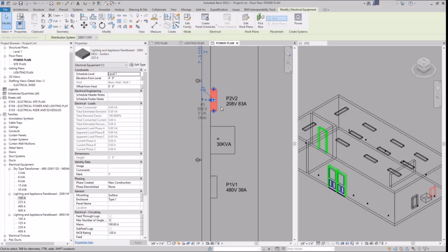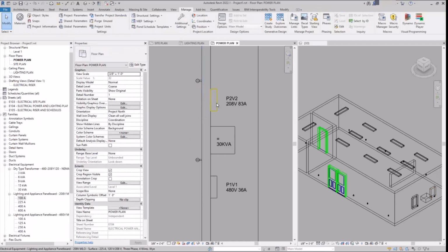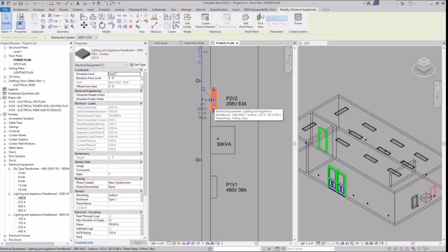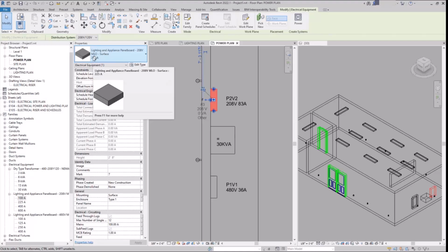Of the breaker, not of the entire panel size. Exactly. So if we were to put a 150 amp breaker in this 225 amp, like I said, just call it a MCB, 225 amp MCB, it could handle 150 amps for 3 hours, and then after that it would trip. If it's an 80% rated breaker.